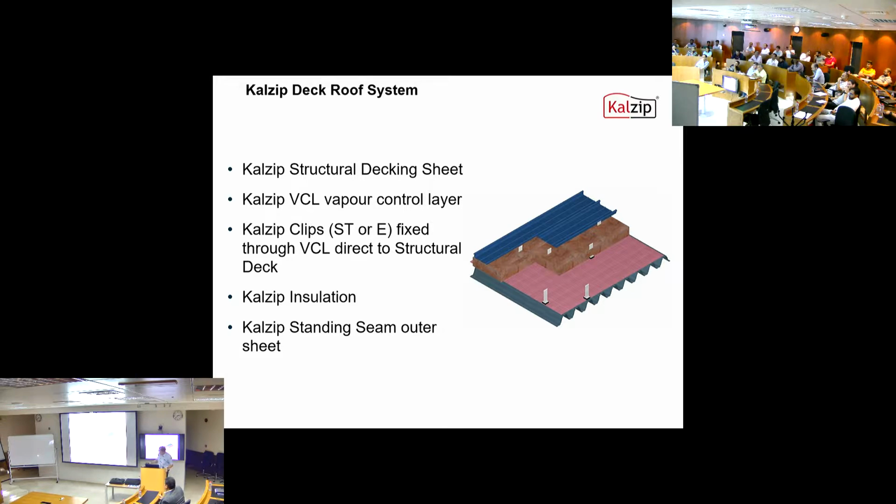So you've got the variable control layer, the clips. The clips are set out in a diagonal orientation, so the external loads are spread evenly onto the deck profiles. Insulation thickness for U-value performance, and top sheet to suit the project specification.